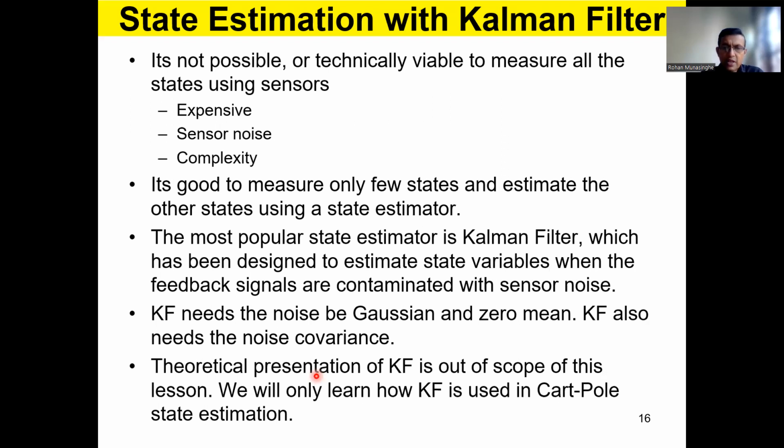You don't read it and send it to the controller and generate the control signal. No. What you do is you send it to the Kalman filter and provide other signals also to the Kalman filter and ask the filter to tell the position. The Kalman filter will give you the position which is slightly different to the actual sensor signal. And the estimate of the Kalman filter would be more accurate than the direct sensor signal.